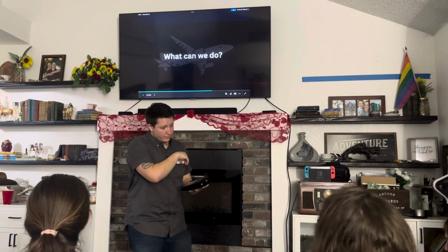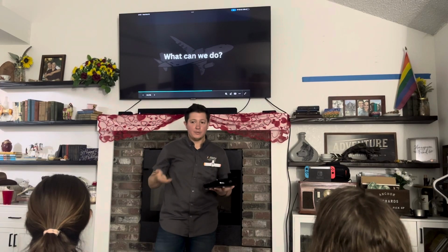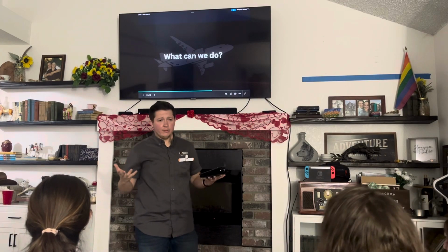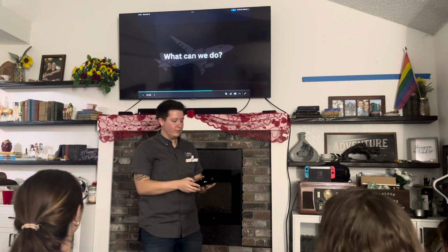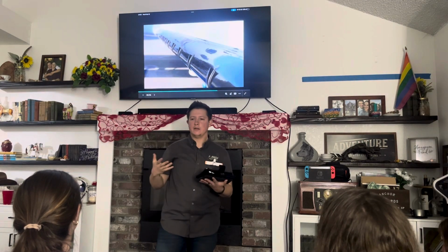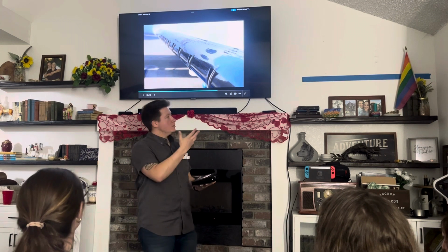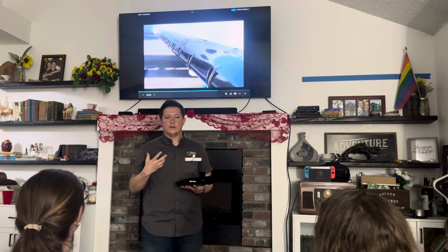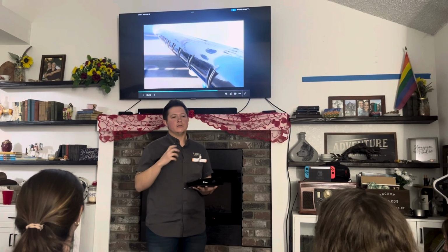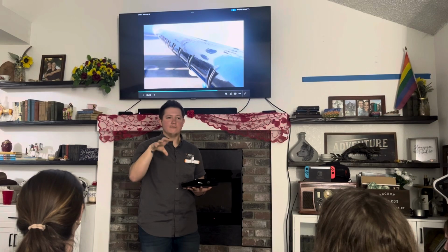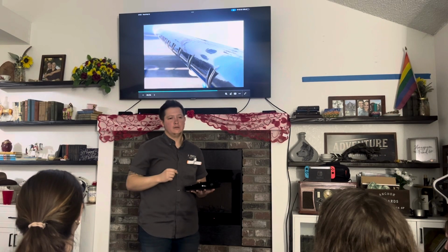So what can we do? I mean, you don't want that to happen. We can't get ourselves out of that situation. How do airlines fly through ice? Well, they have different kinds of systems that can either de-ice or prevent ice from happening. So this is just one of the examples. This is called a leading edge boot, and basically it's a rubberized system that goes along the leading edge, pneumatically charged to basically inflate and just knock all that ice off.